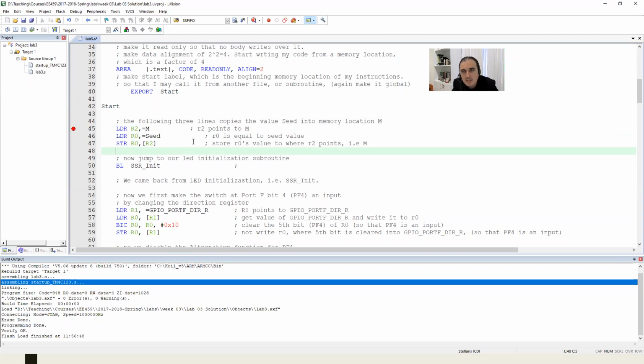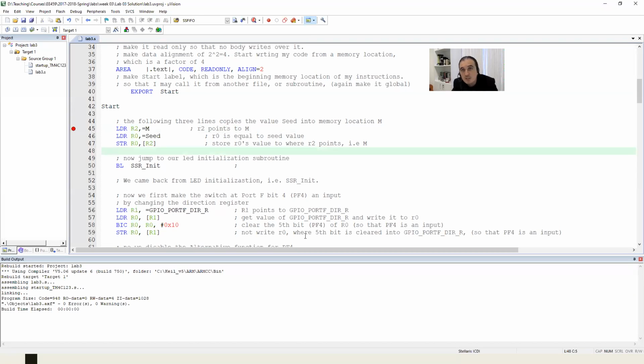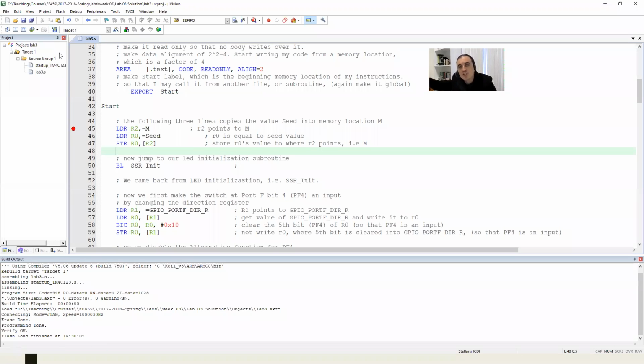So guys, there is this compile operation. And when does this compile operation take place? I press save, and when I say rebuild or build, it is compiling. Actually, it's converting your code to machine code. Now it's machine code. When I say load, it is being loaded to the instruction memory of your card. That's how it happens in all embedded programming. This is the way it works. This is the framework of how you program embedded systems, guys.